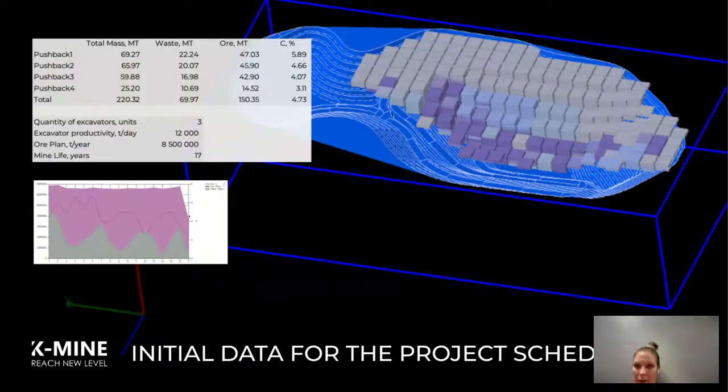So to create a mining plan, we need two parcel boundaries that were defined by the pit optimizer model and worked out in the automatic design mode. This is the basis for creating a subsequent plan, since the pushbacks will be used as delimiters of planning areas of the block model. Also, some additional data will be needed. Our plan will contain planning intervals, years, and will cover the entire life of mine. And therefore, we can say that this plan will be something between long and medium term.